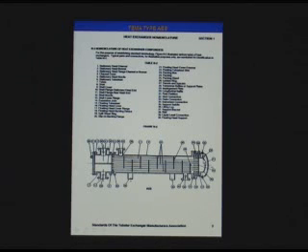This is called a floating head. It has a mechanical split ring which would hold this cover onto the floating tube sheet here, and basically that would allow the fluid flowing into the channel, through the tubes, down, turning around here, and then flowing out the outlet. That basically would define the tube side pressure boundaries for this type of exchanger.